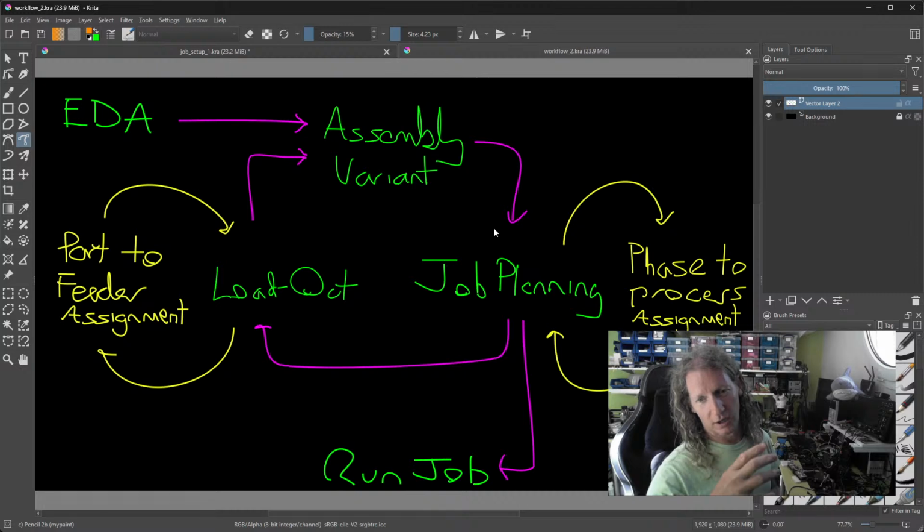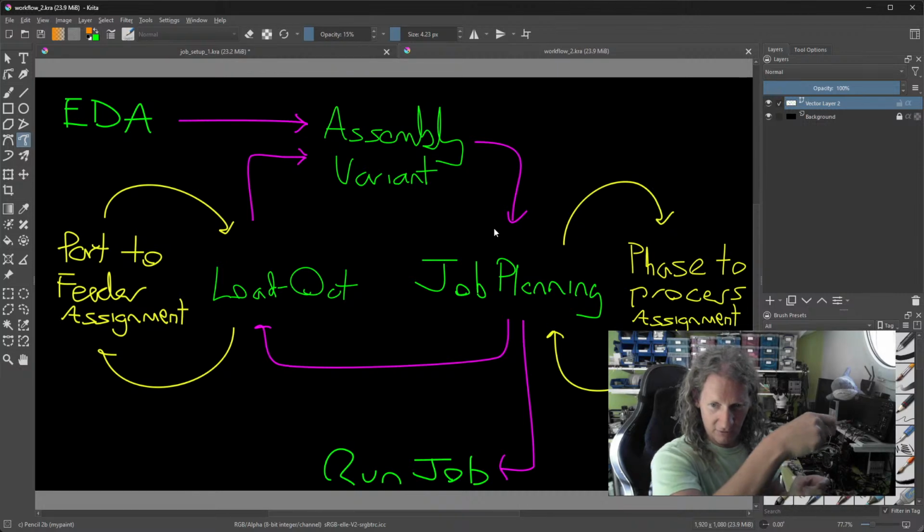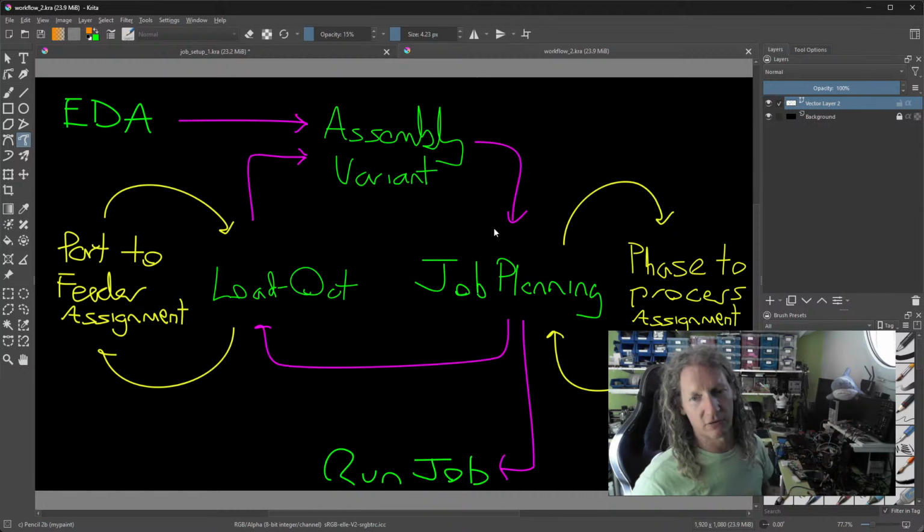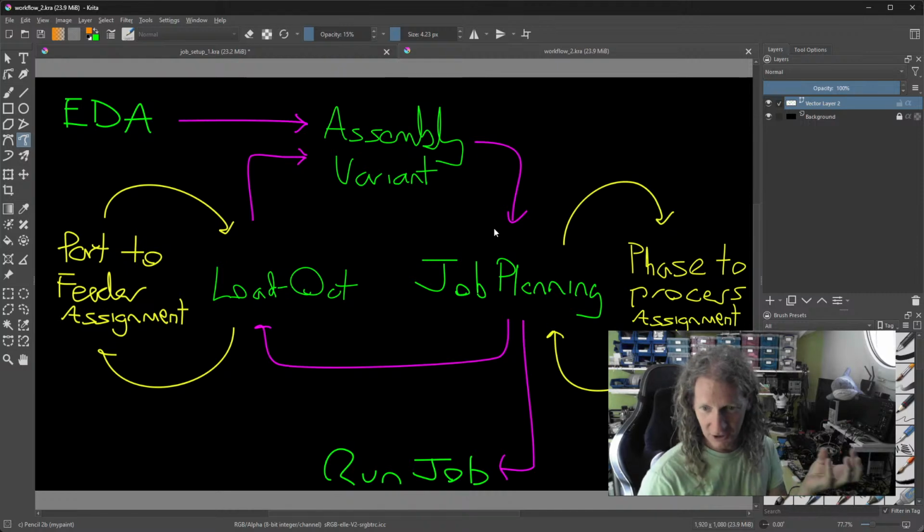Sometimes also you might have a reel with sticky glue on the cover tape. So you've got the reel, and it's got the embossed tape, the bit with the holes in it, as in the plastic or the paper part, and then it has a bit of cover that goes across that. And when you peel that cover off, it gets wrapped around a peeler, but before it gets wrapped around this peeler, it goes over a rod, or it goes through other mechanisms or around stuff on different machines. And sometimes this glue is really sticky.